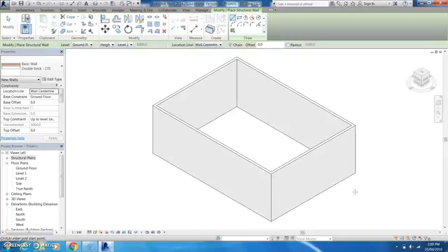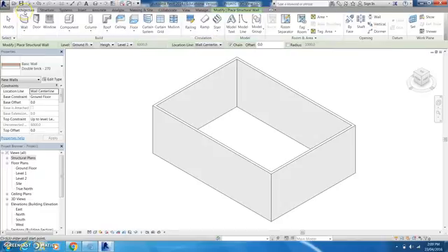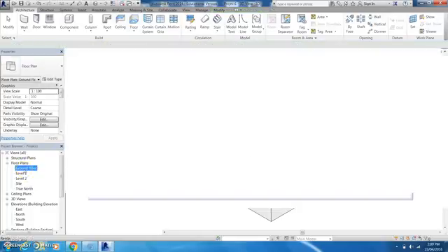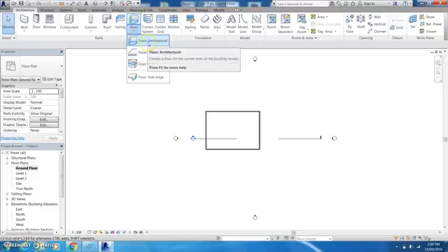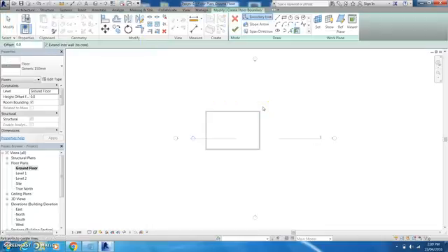as we've already demonstrated. So next thing I'm going to do in my absolute basic of basic houses is I'm going to come back into my architecture and I might put in a floor. Now to do that, I'm going to go to ground floor, select my floor, okay, and this has brought me into this modify mode.